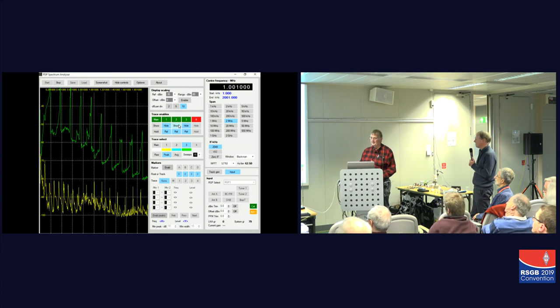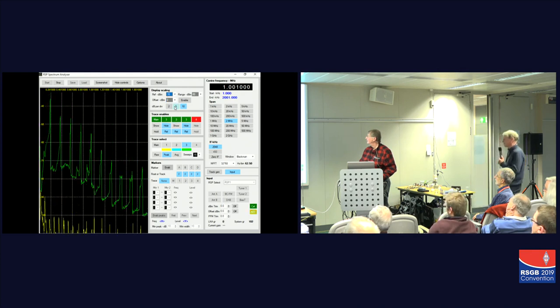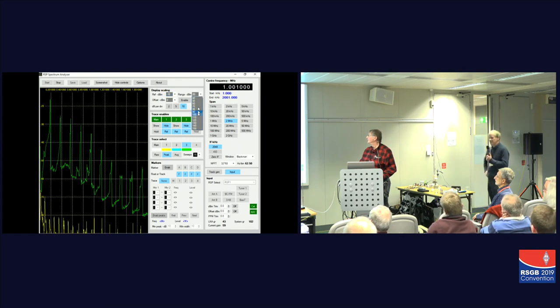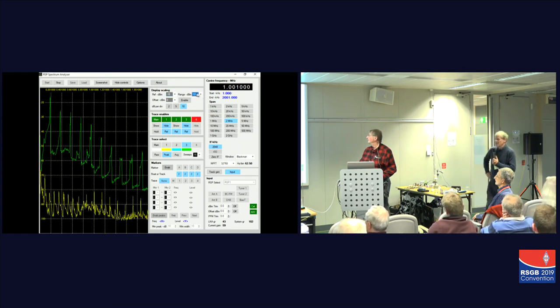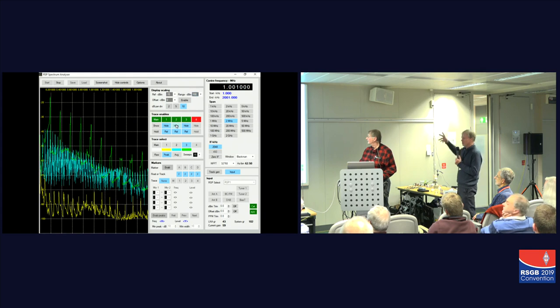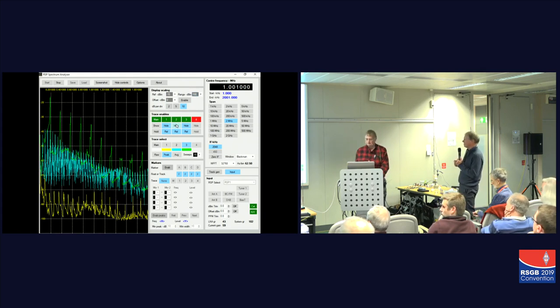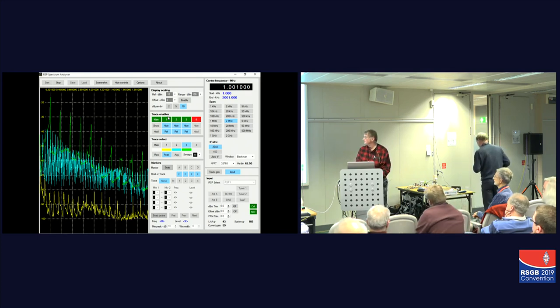So it's absolutely end stop. It's not only got no RF interference filtering, but it's also got no smoothing capacitor. So it puts out an awful lot of ripple onto the mains, and there's no filter to stop it. Well, there we are. So that's LED lighting for you.